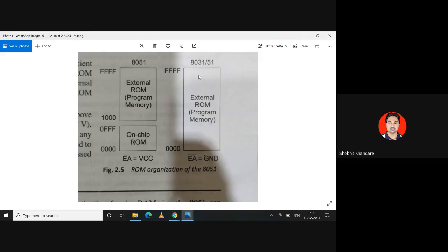डू यू हैव एनी क्वेश्चंस रिगार्डिंग दिस? तो सेकंड केस में तो एक्सटर्नल रोम 64K का होगा ना? हाँ हाँ बराबर है. सेकेंड केस में एक्सटर्नल रोम 64K का होगा, फर्स्ट केस में एक्सटर्नल रोम 60K का होगा, क्योंकि इंटरनल ऑन चिप रोम हम 4K का यूज कर रहे हैं और 60K का रोम हमको अलग यूज करना है. यू आर राइट. फर्स्ट केस 60K, सेकेंड केस 64K.